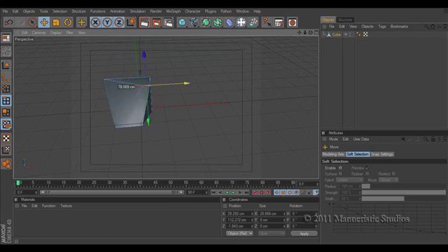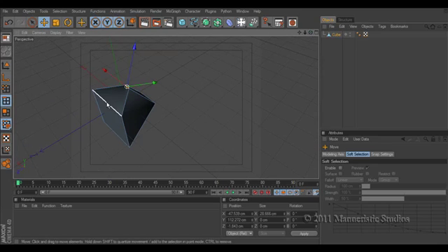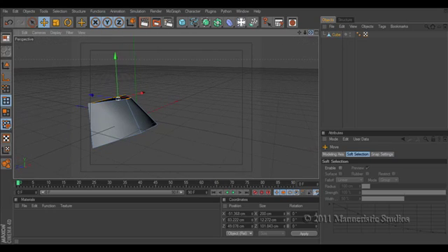And again, I can move this around, and if I want to select a number of different edges, I can by just holding down my shift key. I'm going to select this back one here, and then I can move both of these up. You see if two or more edges are actually selected that parallel each other, the whole polygon face moves in that direction or scales in that direction. So that's just a quick note to remember.